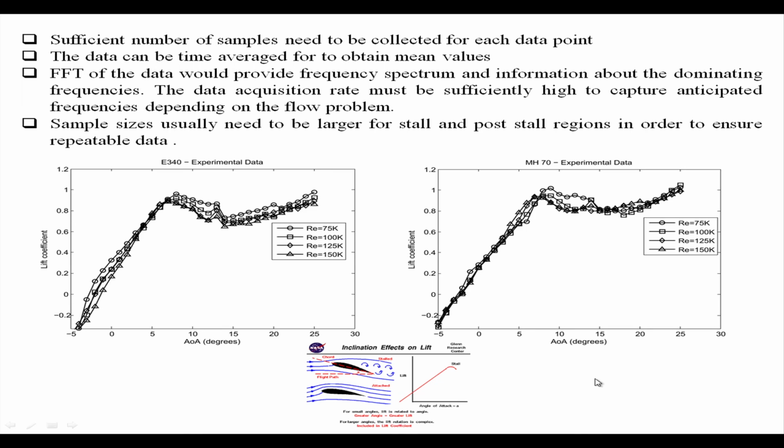And what we saw was that in the linear part, as we call it, low Reynolds number behavior is very peculiar, even in the lower angles of attack, where we generally are familiar with very linear behavior, it does not always happen here. That is our direct experience. We have done these measurements many times.